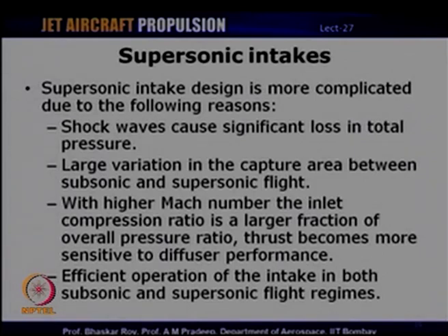The other challenge is the large variation in the capture area between subsonic and supersonic flight. That is, capture area refers to the imaginary area in the free stream which is actually delivering the required mass flow to the engine. And as the engine operates from subsonic to supersonic flight, the variation of this capture area is substantial as compared to subsonic intakes, where the variation of area is not that high.